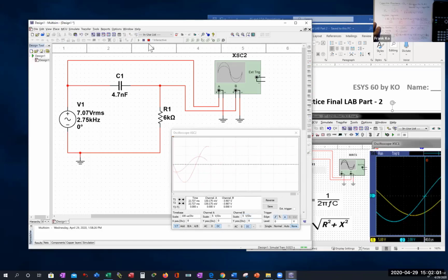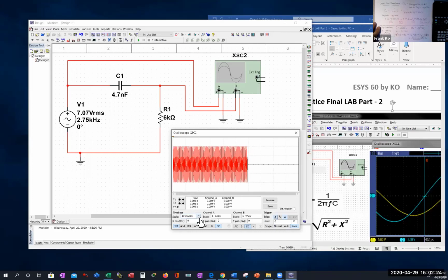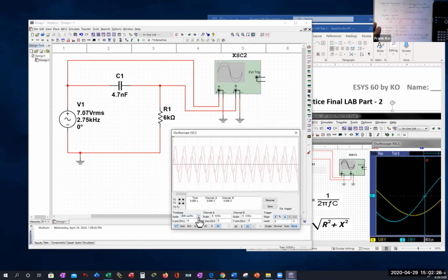So I'm up here, I'm hitting the red square at the top, follow my pointer, red square. If I hit the red square, it stops the wiggly waveforms. Then you come over here, bring this cursor over so you can see the waveforms, now nicely separated. Adjust your time base to avoid this type of pattern initially. Adjust this so you can see these waveforms nicely separated.